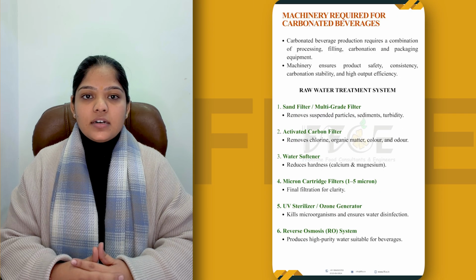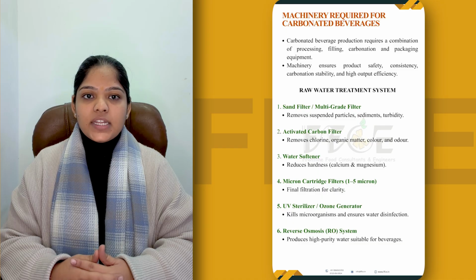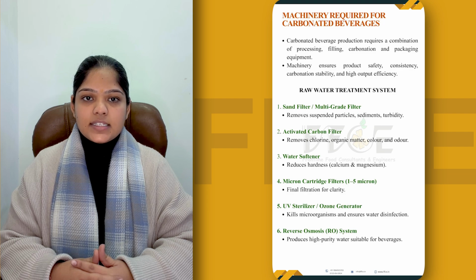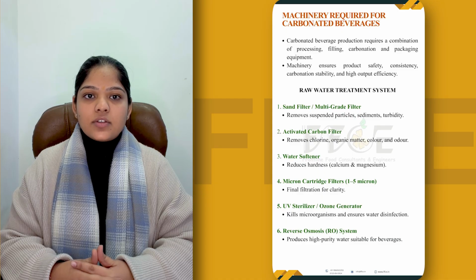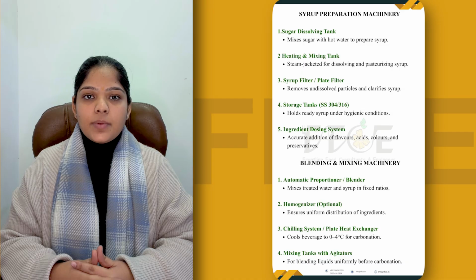For water: water is the most critical raw material in carbonated beverages, contributing nearly 90% of the final product. Therefore, a robust raw water treatment system is essential to ensure safety, taste, consistency, and regulatory compliance. Raw water treatment system key equipment are multi-grade sand filter, activated carbon filter, water softener, micron cartridge filter, UV ozone disinfection, reverse osmosis system. So now for syrup preparation.